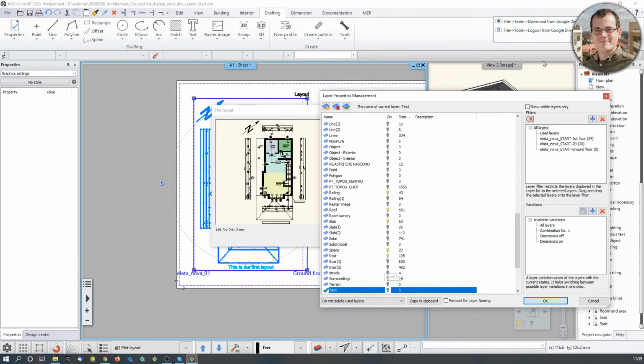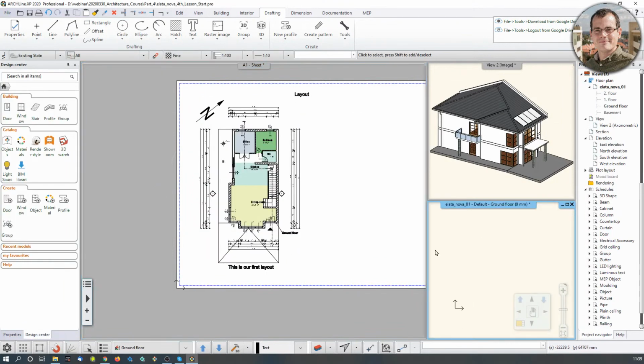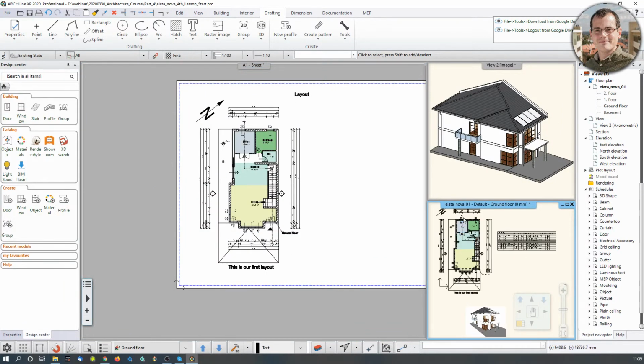One important thing, and that is one of the tricks that I picked up along the way: when we talk about layers, we not only have layers in the 2D, in the 3D, but also on the layouts. So that's very important. Use the layers to manage what you want to hide, what you want to enable. And that is actually what we wanted to discuss now.